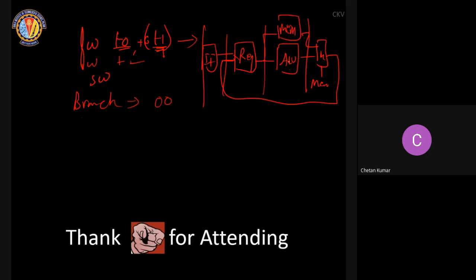So both of them can be put in parallel in a single stage. Okay, so that was the advantage. Your clock cycle period will reduce. Of course, they cannot actually run in parallel because it's a single-cycle implementation. Only one instruction will be in the entire data path at any point of time.